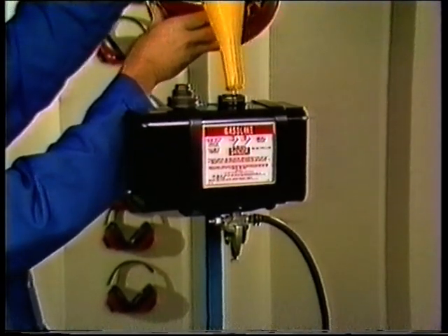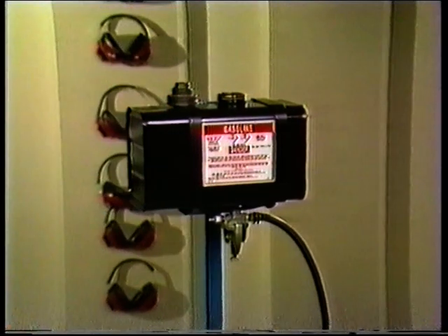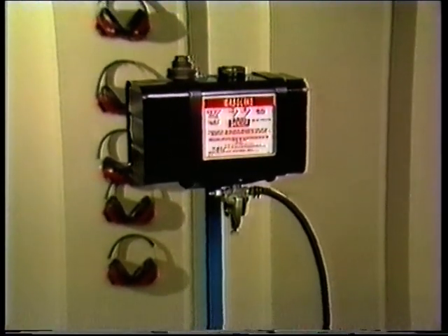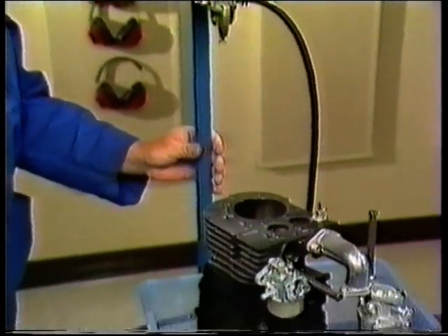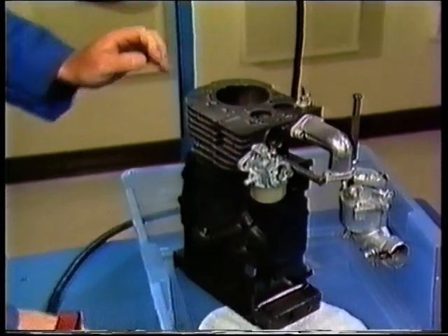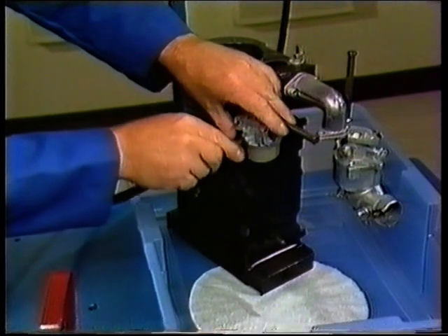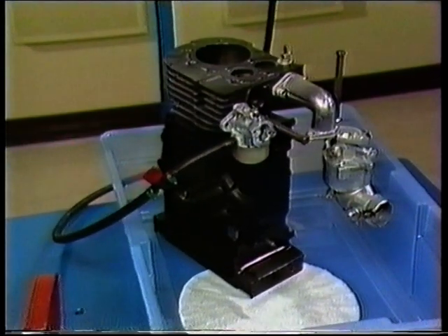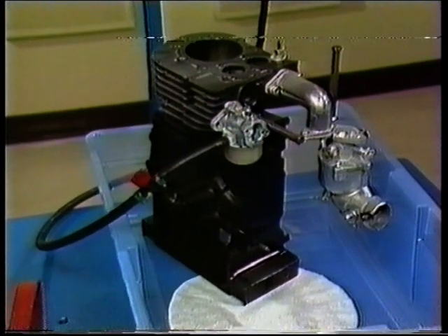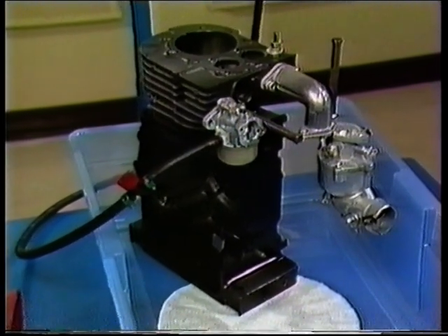Fill the tank with gasoline and place it between 12 and 18 inches above the test bench. Measure this from the top of the fuel tank. Attach the fuel line to the carburetor you're testing and open the inline fuel shutoff. Place a piece of paper under the carburetor and let it stand in a catch basin or drain pan overnight. In the morning, you'll know whether static leakage is a problem or not.